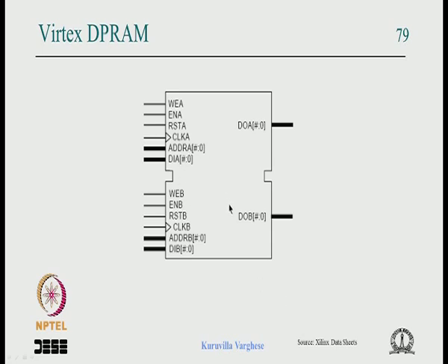If it's the same location of course there will be a conflict, if one port is writing and one port is reading the same location. Then there is a problem, what is read may not be correct. And you should also know that there is a great thing about input and output data lines. In a normal chip they are multiplexed together to save pins, but here it is ideal to have separate input and separate output, because you don't need a mux select, like you don't need separate write and read select and all that, which avoids that. So that is how the dual port is implemented.